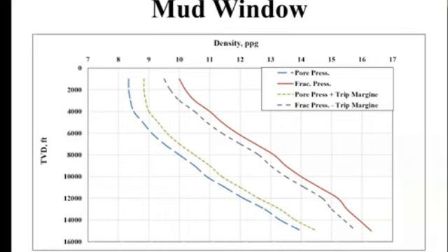So when the drilling fluid is moving upward, friction or pressure drop due to friction is acting downward. So bottom hole pressure will be the pressure drop due to friction plus the hydrostatic pressure of the mud column inside the annulus. So bottom hole pressure is more than static pressure.